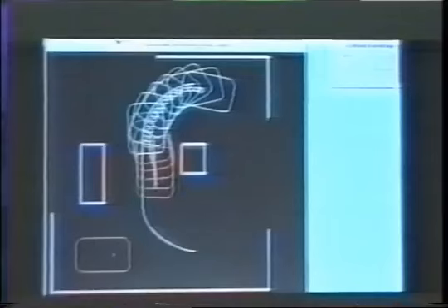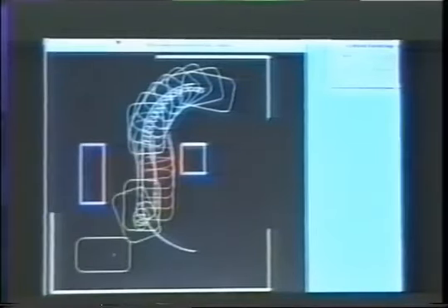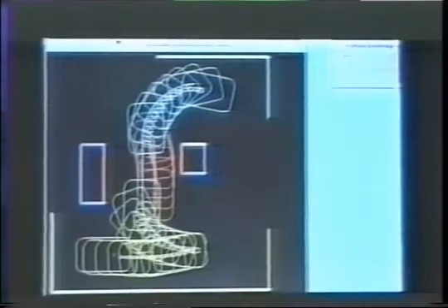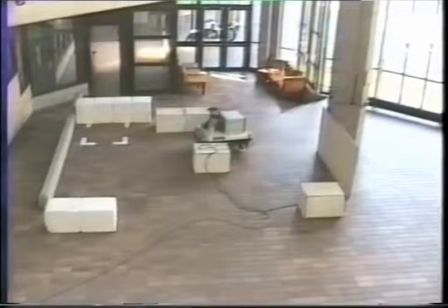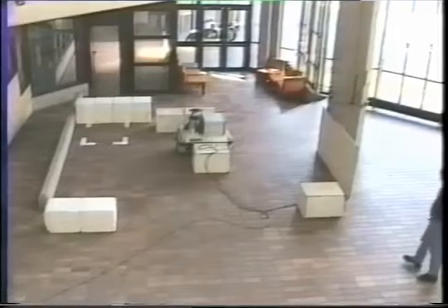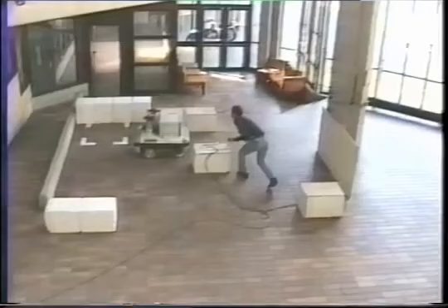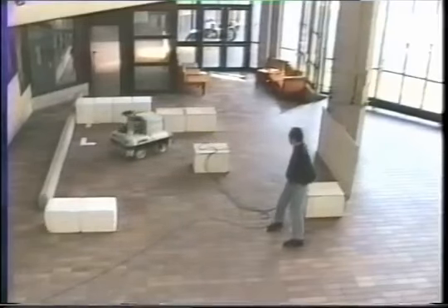On the control screen, we see how this is interpreted by the robot when the local map changes. We see the discontinuity in the estimated position due to the fact that the new reference frame is not at the expected place with respect to the previous one. The stabilizing control law finally compensates for this and leads to a successful completion of the mission. This is the corresponding reality where we can see another type of disturbance due to the umbilical cord.